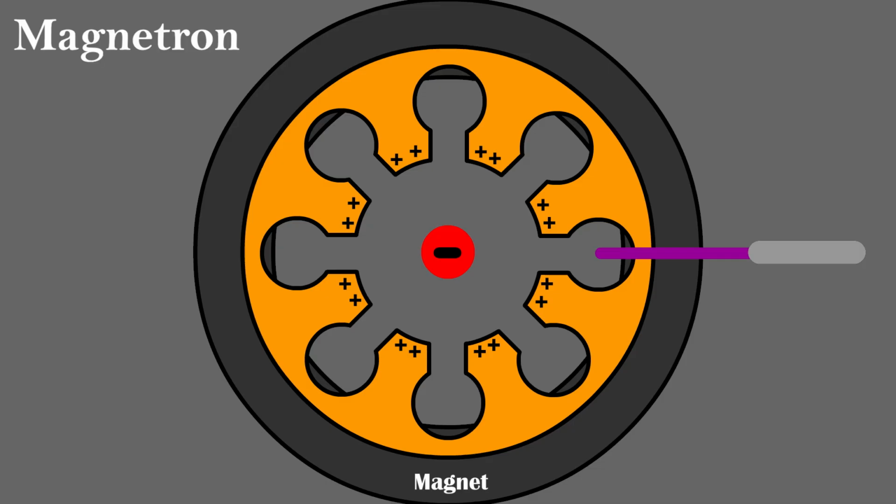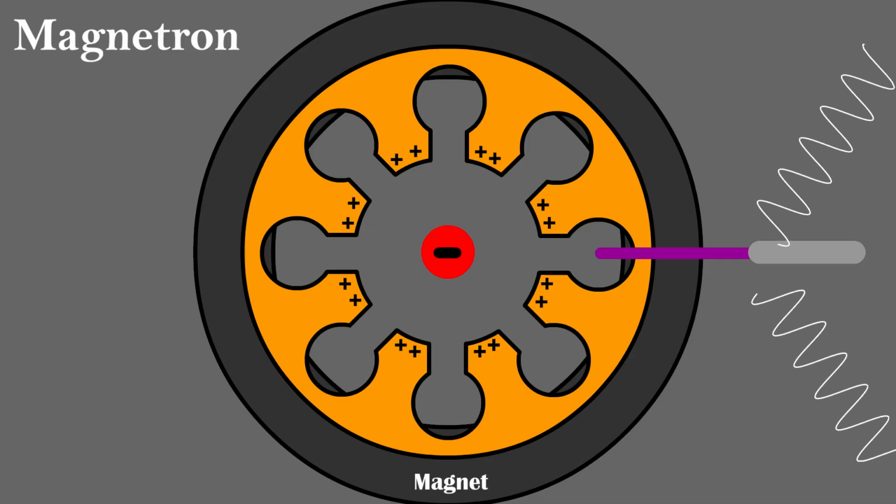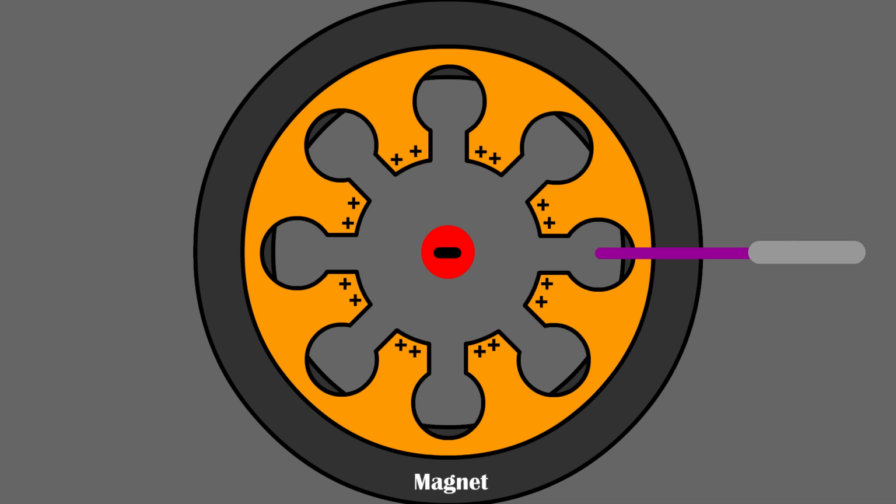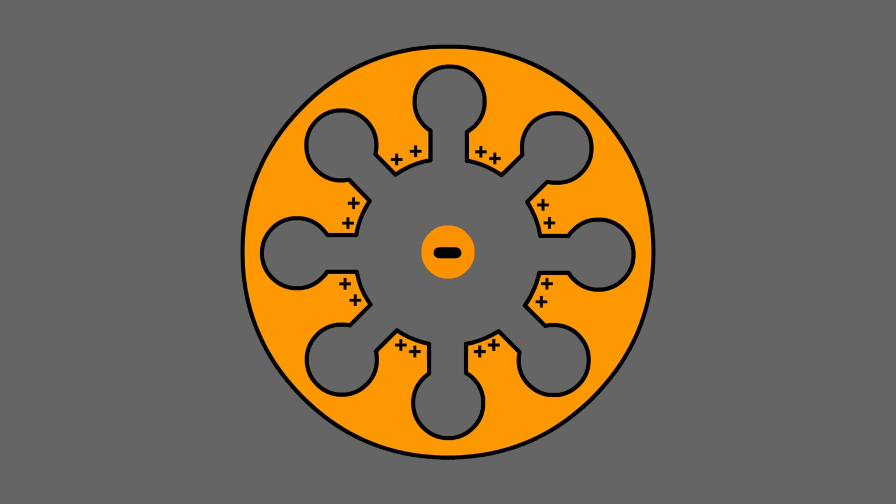The magnetron emits electromagnetic waves as a result of electrons accelerated by an electric field and then influenced by a magnetic field. At the center of the magnetron, there is a filament that acts as an electron source. When this filament is heated, it emits electrons through thermionic emission. Surrounding this filament is an anode structure with gaps, similar to a capacitor, held at a positive voltage.